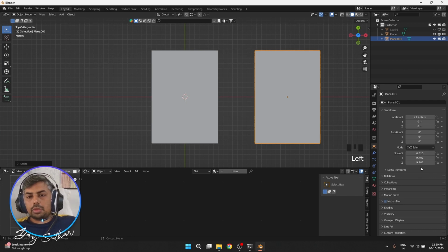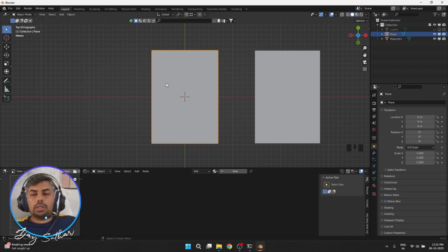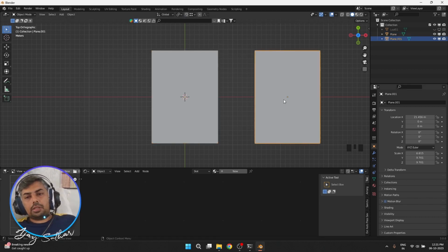See this. Now whatever the effect or modifiers or any action which helps to edit this object will only work according to the overall scale. It might create a stretch and squash effect in the design, but here no action, no effect, anything. I can do anything with this object. Why? Because I have scaled this object in edit mode, not in object mode. If scaled in object mode, it will affect inside the edit mode and also on the object mode. But here no issues, it's all clear. We can play in our own created playground.